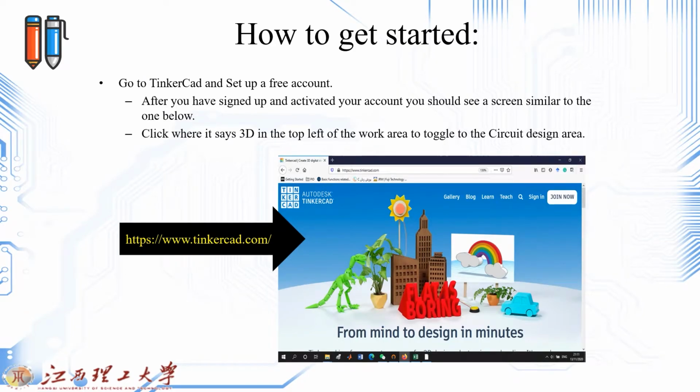But really, how do we get started with this nice simulator? This is the part that we are going to discuss. If we want to touch on this web page, we can simply go to tinkercad.com, and after you have signed up and activated your account, you should see a screen similar to the one that I bring here. Click where it says 3D in the top left of the work area to toggle to the circuit design. Let us see the next picture.